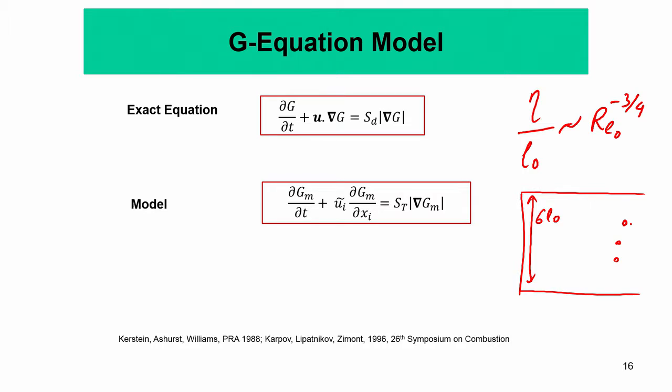So your largest domain size has to be of the order of a few hundred centimeters, and your smallest length scale in your mesh, if you want to do it by CFD, the grid size, has to be of the order of a few microns, right. So, that is the problem.